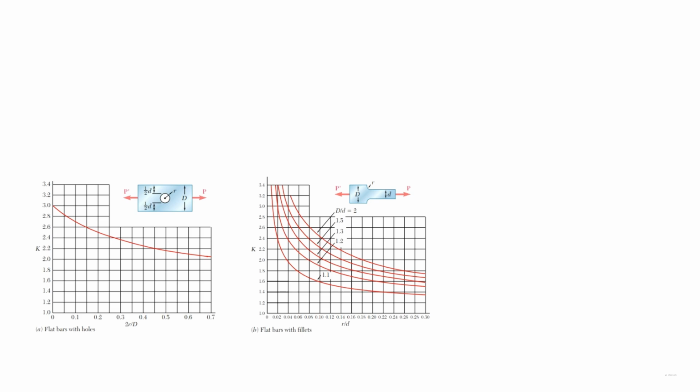So we can say there was a stress concentration near the point where the load was applied. If bodies have discontinuities, such as a hole or a change in width, then there is stress concentration. The stresses near the hole or where the width changes is higher than the rest of the plate.